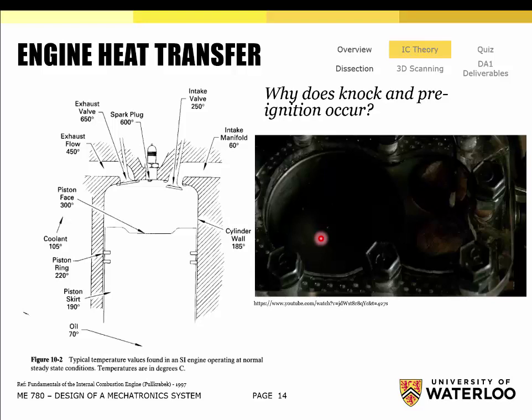So, yes, of course. In this vehicle, is the oil premixed with air or is it injected in service? You mean the gas? The gas. Yes. So great question. Is the gasoline or the fuel pre-mixed with the air, or is it injected inside the cylinder? So prior to entering the intake valve here, the intake port, there's either a fuel injection system or a carburetor. We discussed this a little bit last lecture, but it's effectively delivering liquid fuel that will vaporize into this port and then travel into the cylinder.